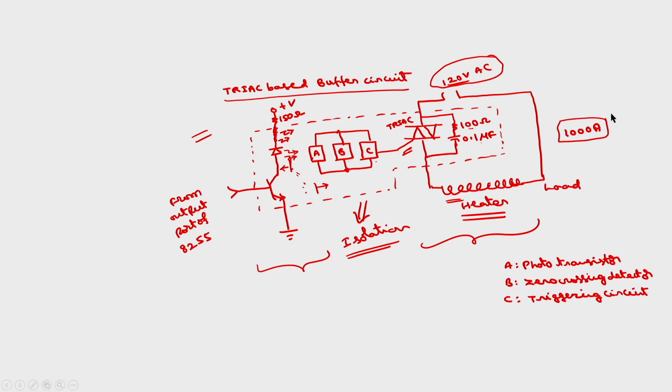So, as the current value increases and the demand of the load is more, we are going to incorporate one of these circuits. We started with a simple IC buffer, where the current capacity is somewhat less. Then to increase that we went to the transistor buffer, but with a single transistor the current capacity is still low. So, we used two combined transistors, a Darlington pair. To further improve the current, we went to the MOSFET and IGBT. To improve it further, we can use the triac. So, these are the various circuits which will produce more currents, thereby you can drive high power devices.